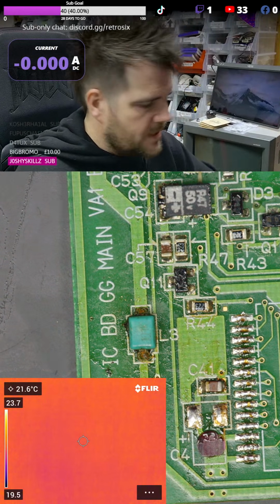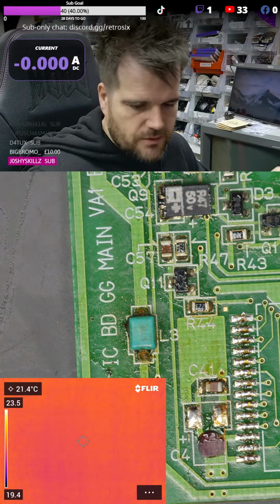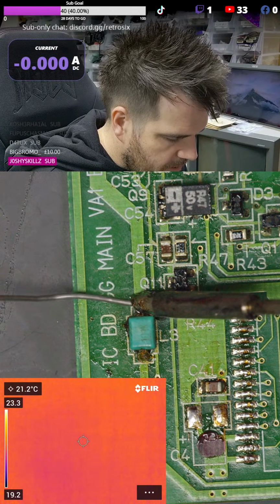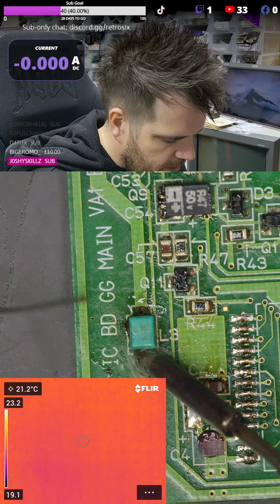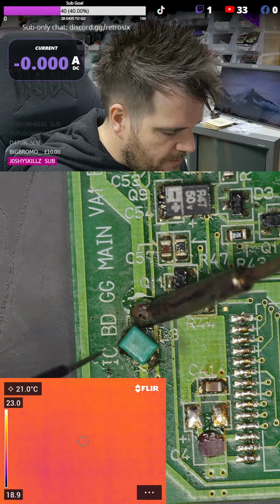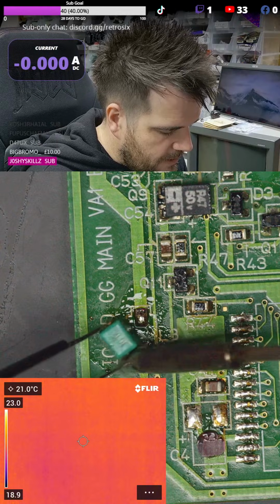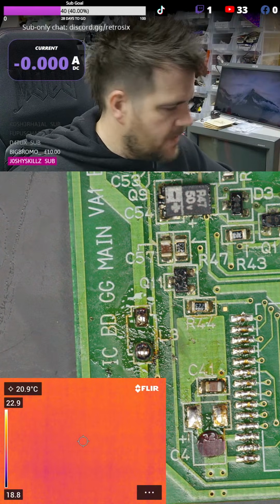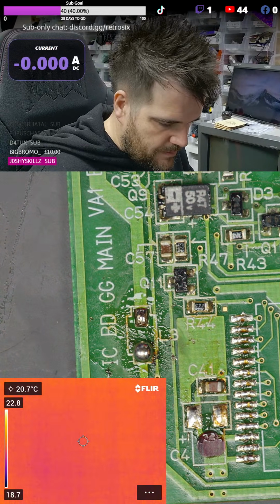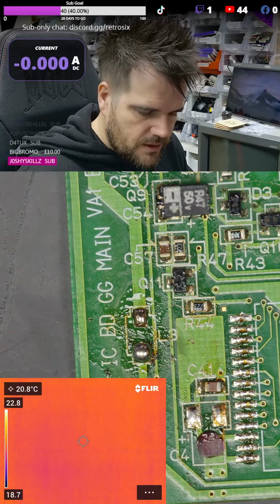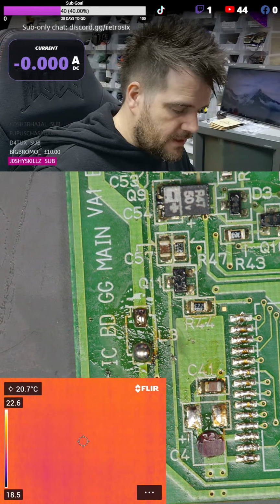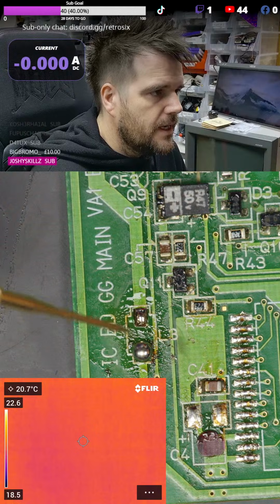So what you'd do in this case is you would remove this inductor. So let's just try removing this like so. And this is where your bench power is going to come in handy. If you've got a bench power, this is where it's super useful. Take it off the input, off the mains. So now what I've got here is, I can now inject voltage.